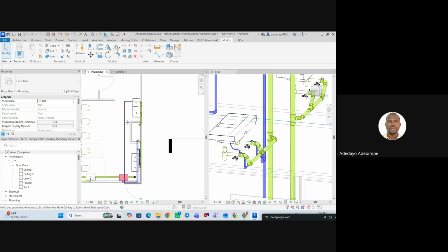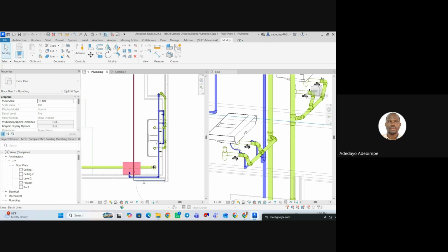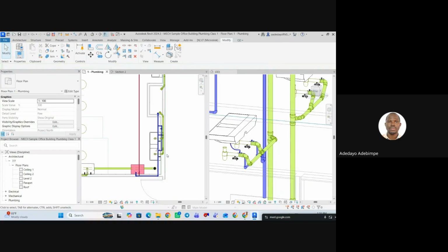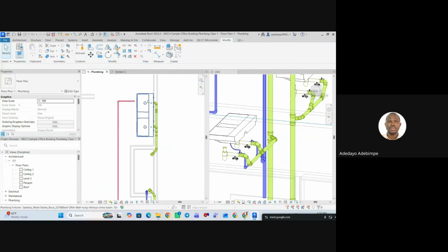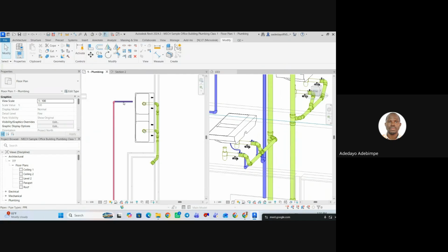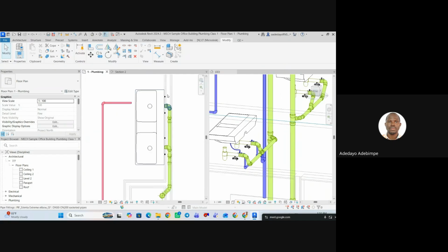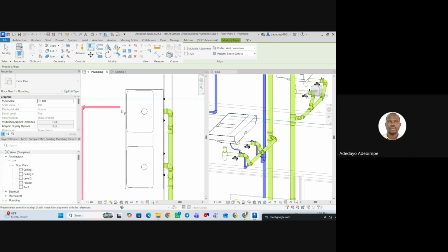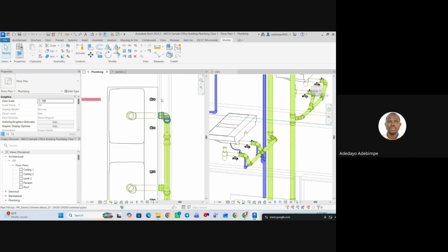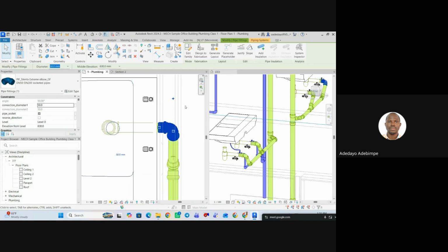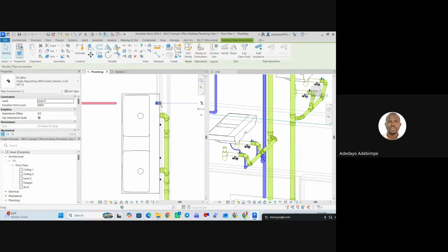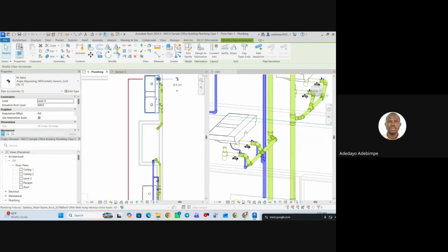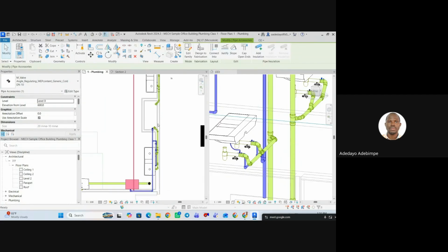Now, to follow our proposed pipe route, permit me to just delete all my detail lines. So we are connecting to each of the hot water connections from high level. Permit me to do AL, align. I want to align this last point. So this, then I'll click on my hot water angle valve and stay. Okay, we've not routed our pipe for this side.